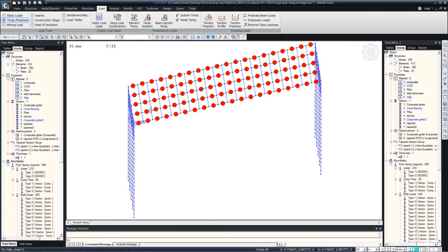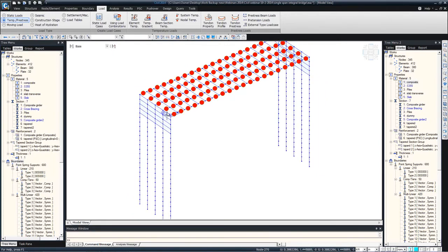If it is a grillage model, then we can go for some dummy beams modeled here, just to represent the extent of the loading. So you can create some dummy beams in between with little stiffness or smaller cross sections like 10 millimeters by 10 millimeters, for example, and just apply the loads as a floor load on those members.